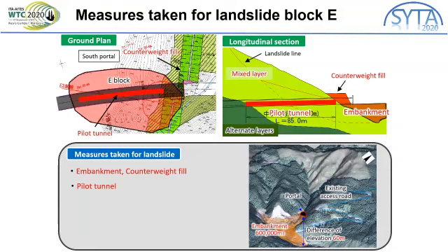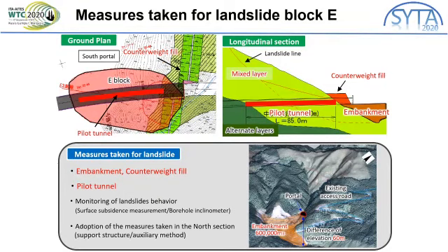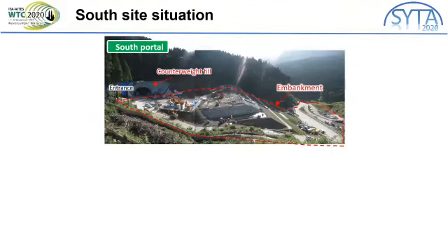Before the excavation of the main tunnel, the pilot tunnel was advanced to monitor the landslide behavior and to investigate the geological conditions. The support structure and the auxiliary methods were adapted as same as the results of the north section. This slide shows the situation during the excavation of the pilot tunnel from the south portal. The red dotted area indicates the embankment with the valley backfilled.